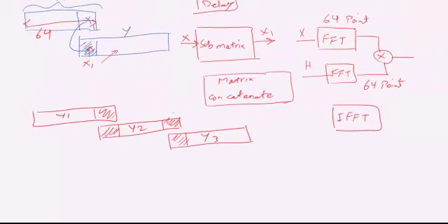So in order to do that, you have to do something that you already did for merging, with the difference that this time you have to do the opposite, the reverse way. It means that you have to remove rather than merge part of the sequence. For that, again, you can use the same submatrix block. After you use it, you can configure the submatrix block in Simulink to remove part of the overlap sequence.